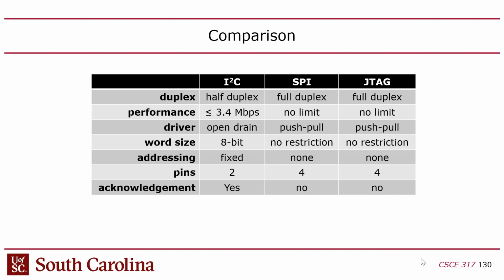when you go to a sleep, it basically assumes that the instructions don't require any time to execute, right? So you say, I've got the duty cycle, I want to set the duty cycle to a certain amount of microseconds, and I'll wait for that amount of time after I set the LEDs high. But it doesn't take into account the amount of time it took to call U-Sleep, for instance, right? And while you were calling U-Sleep, that was extra time you were leaving the LEDs on.